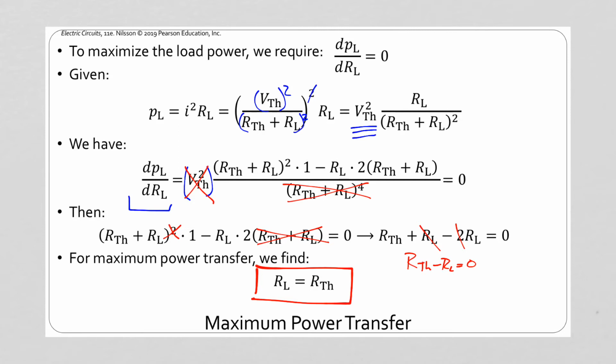And in fact, you'll see this in headphones and antennas and speakers and such, where the internal resistance of that circuit element will have a fixed given amount, so that its load resistance matches the R Thevenin, the standard output resistance that you'd have for a headphones jack or a speaker plug, that sort of thing.